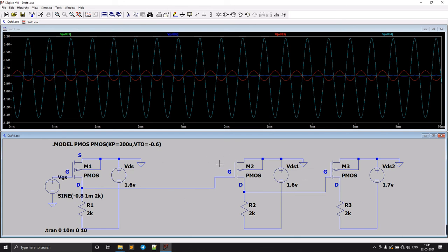But make sure when we connect it like this, we cannot increase the gain further by connecting like this because this has to remain in the saturation region. We need to follow this condition for all these kinds of amplifier circuits we use. All have to be in the saturation region. I hope you understand the circuit.